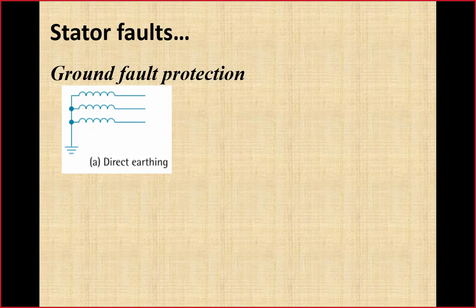So in this condition, no need to have any dedicated ground protection, because fault current through the phase protection will be sufficient. The relays that we have used to detect the phase fault will be sufficient to detect the ground fault as well, because ground fault current is sufficiently high here.